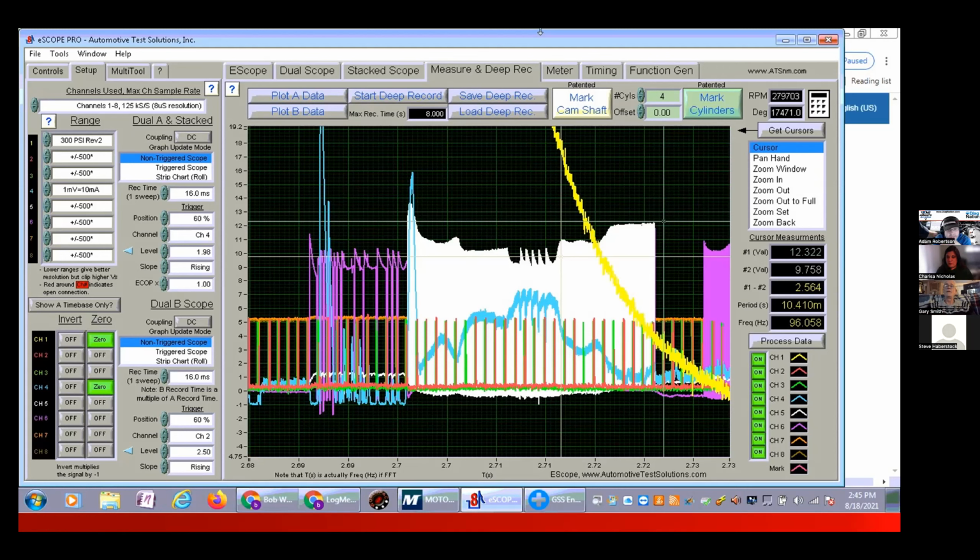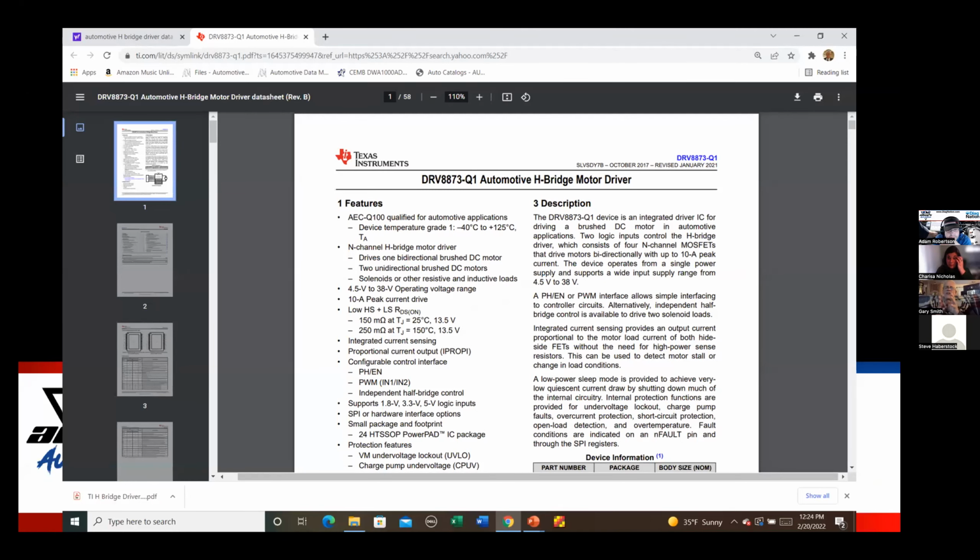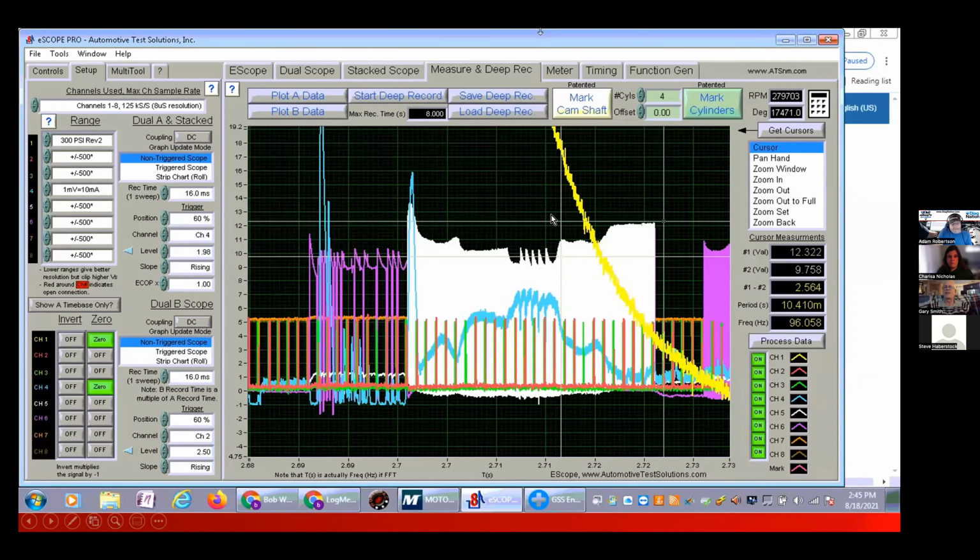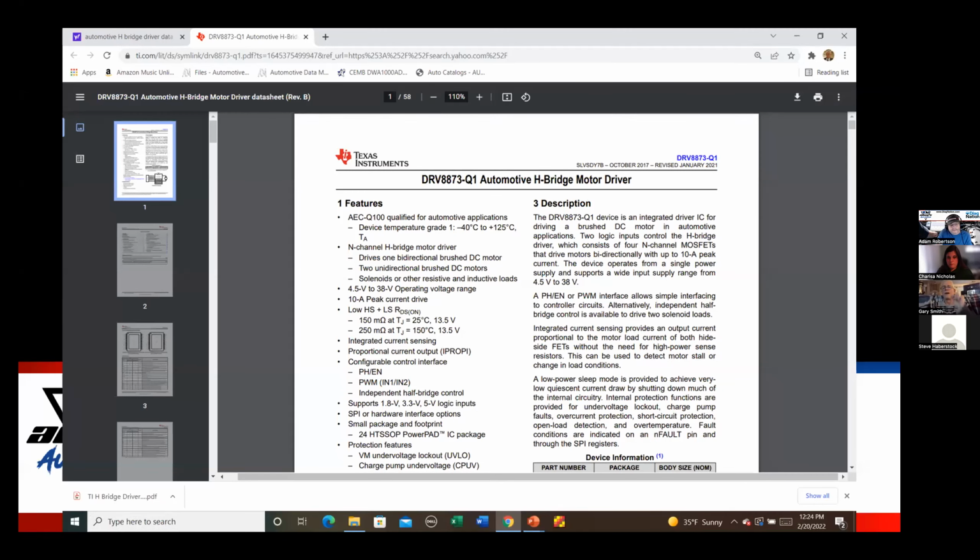That's pretty cool. Now, here's what's neat about researching technical problems outside the box. We know that when you get a picture of an ECM or a DME module in the wiring schematic, it does not draw the internal circuitry. Would everybody agree with that? Which is why understanding signature intelligence on your waveforms, this is a signature intelligence issue. If we understand electronic signals intelligence and we can relate it to what's stated on this chip sheet, what you'll find is the exact answer to what's going on with this car.